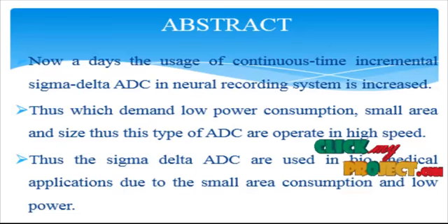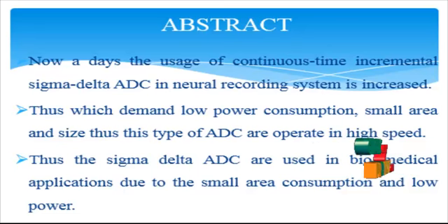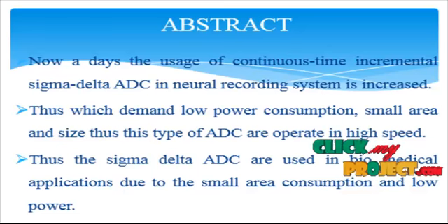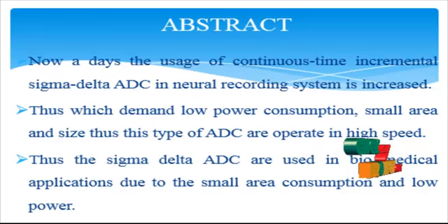This paper presents an analog to digital converter dedicated to neural encoding systems. By using two continuous time incremental sigma delta ADCs in a pipeline configuration, the proposed ADC can achieve high resolution without sacrificing the conversion rate. This two-step architecture is also power efficient, as the resolution requirement for the incremental sigma delta ADC in each step is significantly relaxed. To further enhance the power efficiency, a class AB output stage and a dynamic summing comparator are used to implement